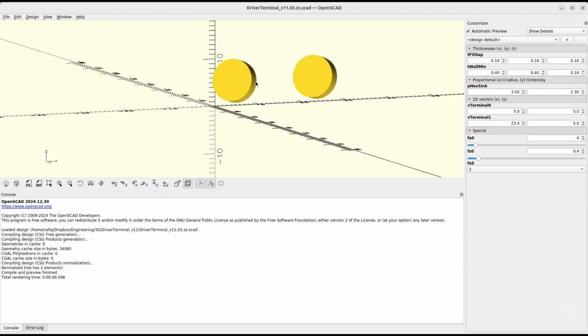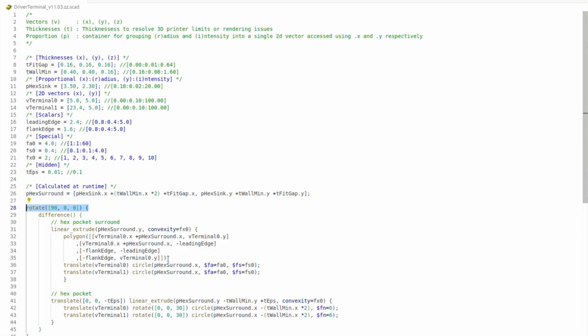So there's 2 things that you should be noticing here. One, all we're doing is we're making a simple rectangle with 4 points. That part's easy. The other thing you're probably noticing is that I'm referencing this rectangle using x and y coordinates. But in our model, the y coordinate has somehow been translated into the z coordinate. Remember, in our 3D space, x is this way, y is this way, and z is this way. But in our polygon, I'm defining x is this way and y as this way. I can do that because of this rotate instruction over here.